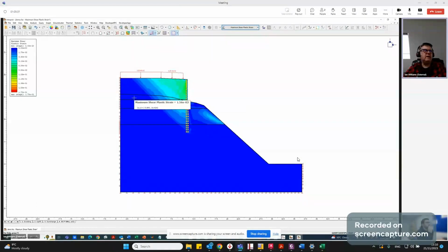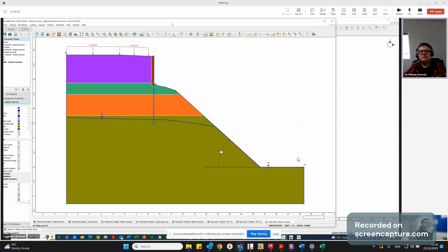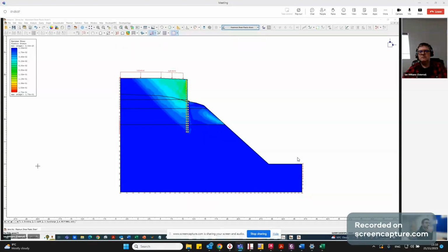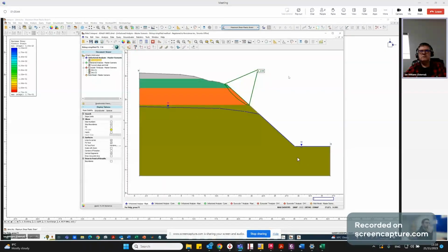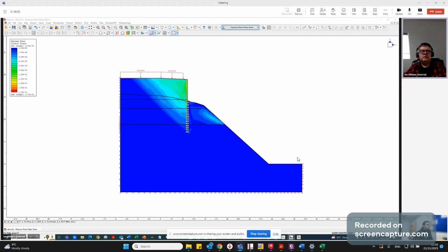If you just took the wall away, if you go back to your Slide model, where's the Slide interpreter gone? No, that's how I read it. Why would you not say a trial pile diameter should never be less than half of the working diameter? You were seeing that slip happening anyway. But this one is saying it's 1.14, so it's not really happening. It's stable. It's more than one. And it doesn't happen at working loads. Yeah, true.